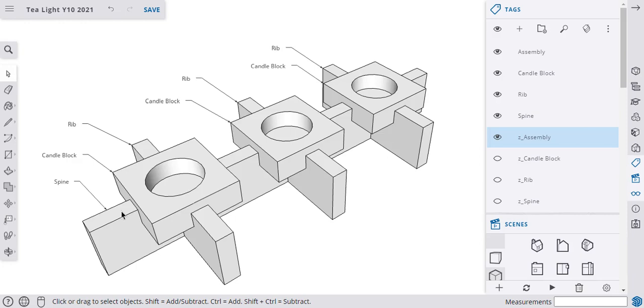You don't have to worry about, I would create the scene now, except I haven't created all these layers. What do I do? What's my work order? Rather create your tags as soon as you can, and then go create your scenes much later in the task. And I hope that helps. It is the step that is necessary to get the drawings out of the model into your design document, onto a piece of paper that you can take into the workshop, and these are both important steps and an important thing to be able to do.